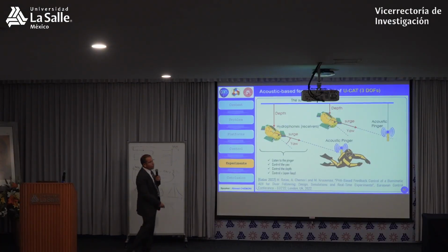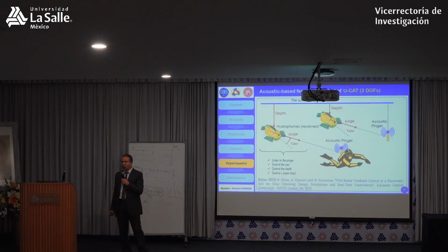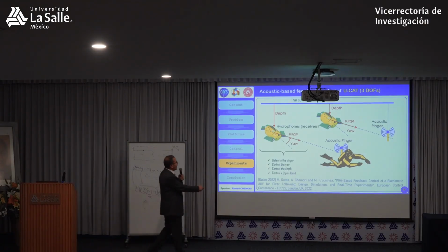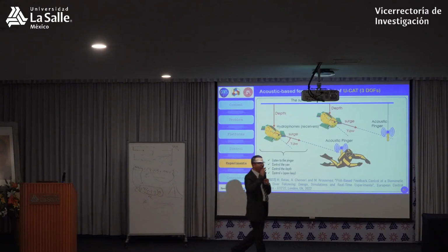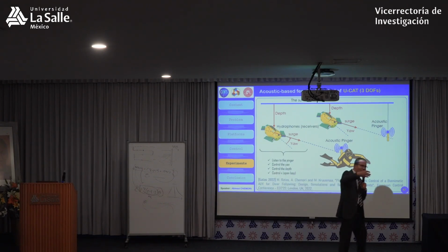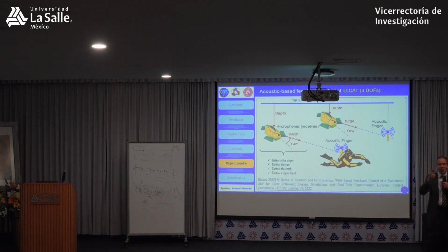Nice, then we try to use acoustic control. We try to use the 3 hydrophones here, but we want to do something in cooperation with the diver. But the diver will not ask the UCAT, come follow me. No, what we did, we used a pinger. This is a pinger. It emits acoustic signals, beep, beep, beep. And the vehicle used the hydrophones to get this sound and try to follow the sound.